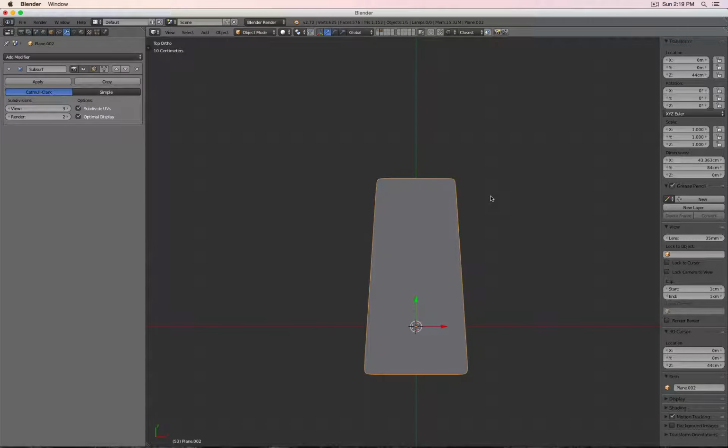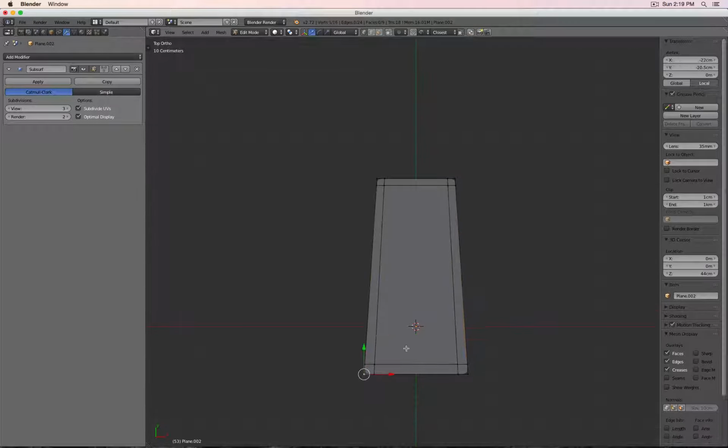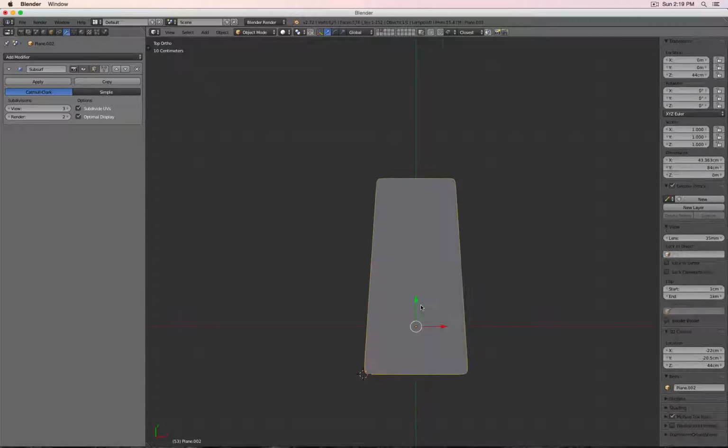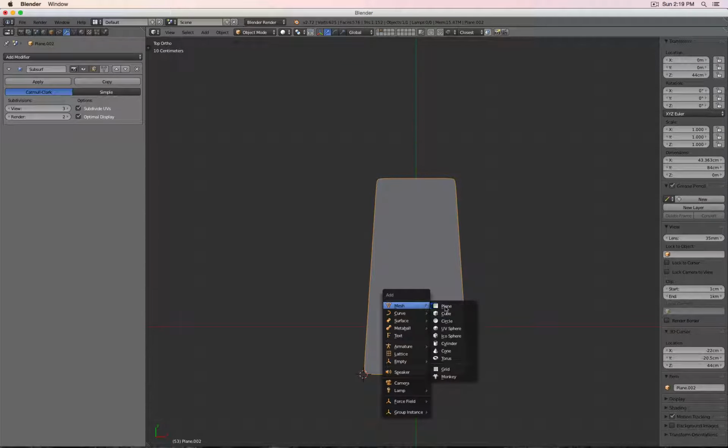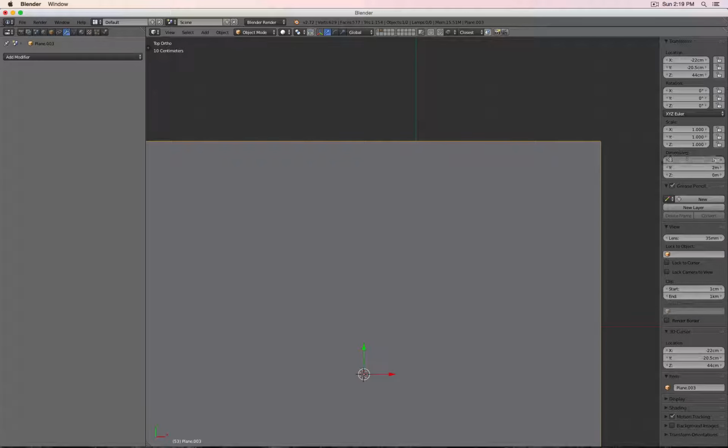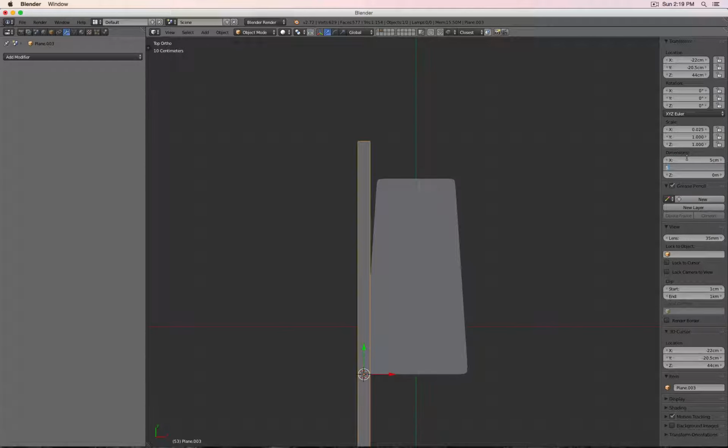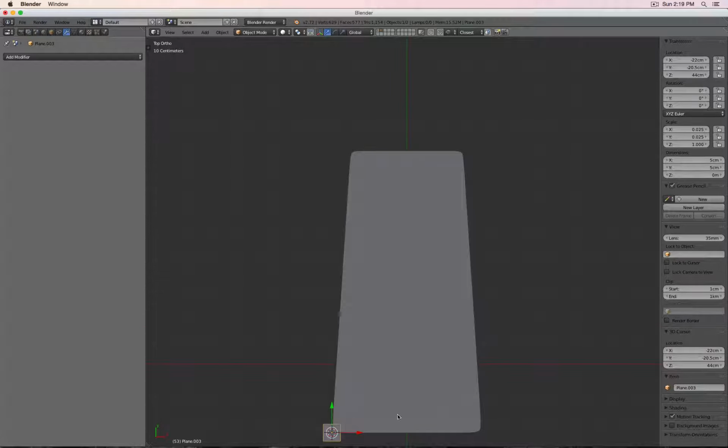Now if you would like to have a little bit more control about those edge roundings, the lower part here, I know, for example, that it should be a 5 centimeter radius. So there I could create a small plane, 5 centimeters by 5 centimeters.